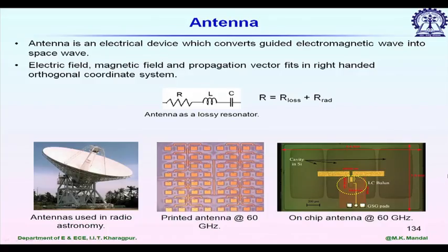When we do so, of course, we face some problems. You can identify there are some cavities. This particular antenna is designed on a silicon substrate, and in silicon we face the problem of surface waves. To avoid that, people use an air cavity just below the antenna, which improves the gain of the antenna.